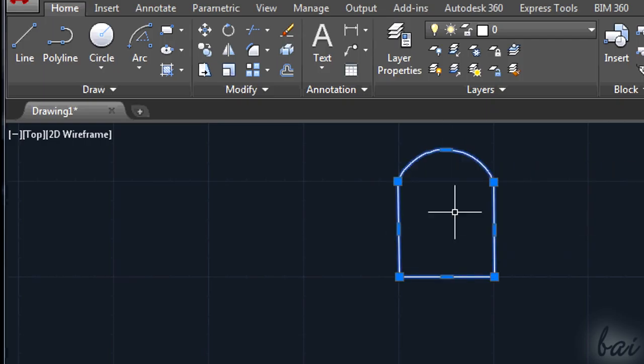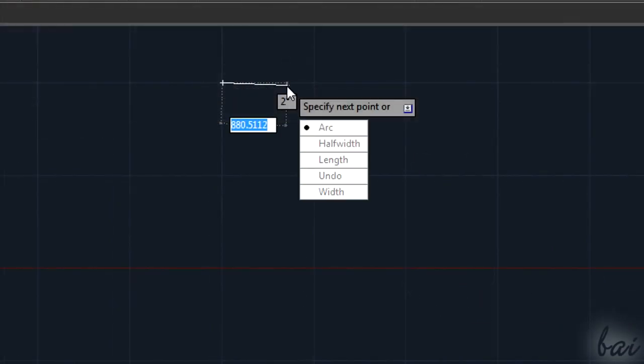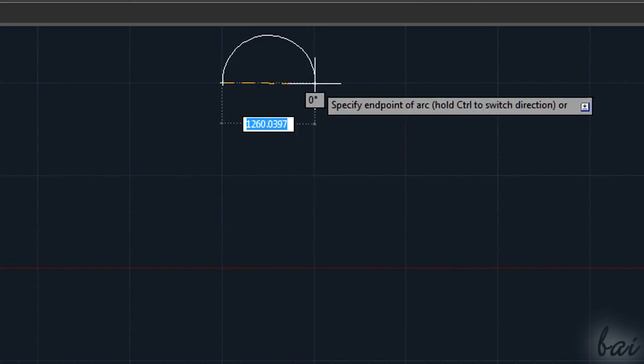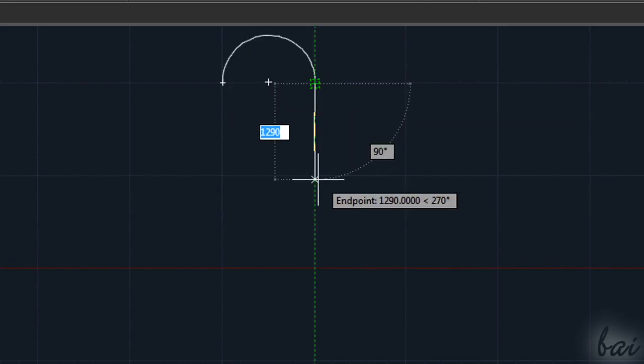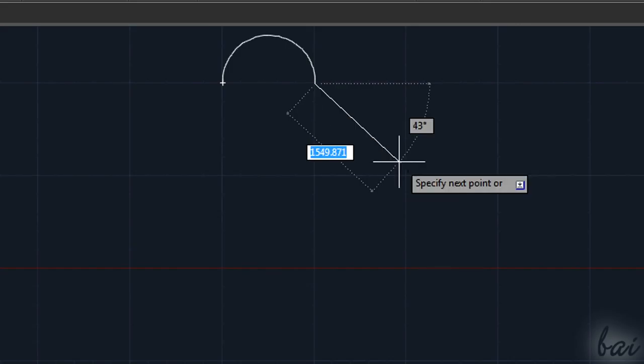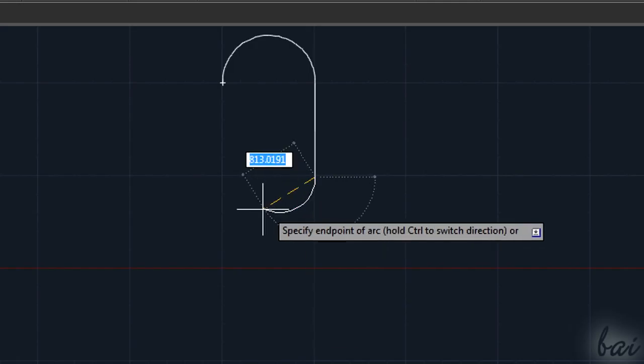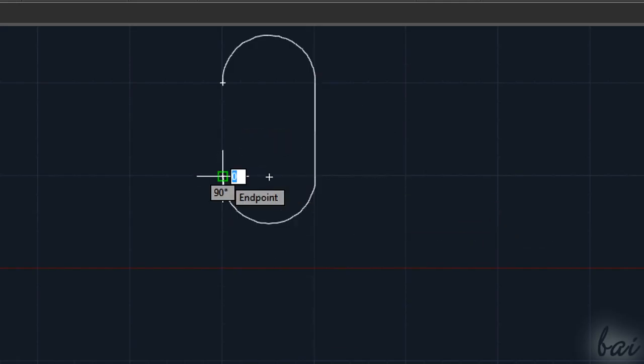You can draw it first as a polygon and then edit it to give curves. Otherwise, you can use the dialog box to insert curves from the start while you draw. To use the dialog box, simply use the up and down arrow keys on your keyboard and choose in the list with Enter.